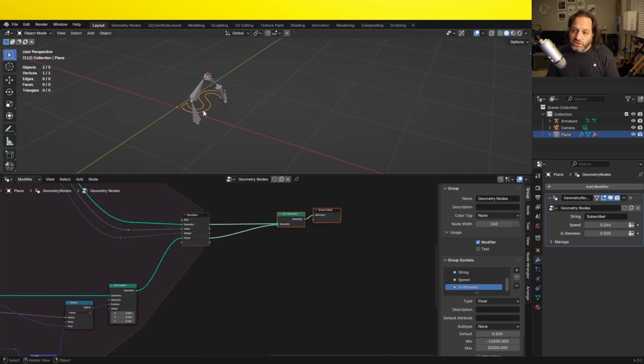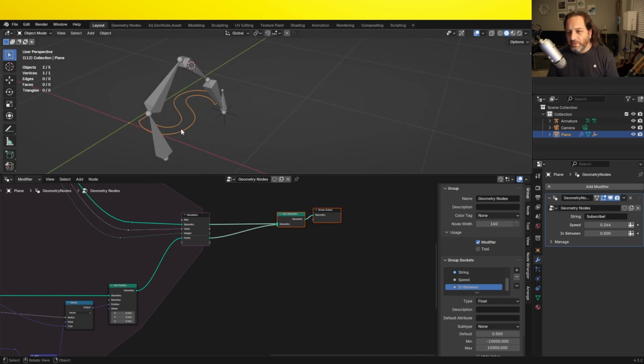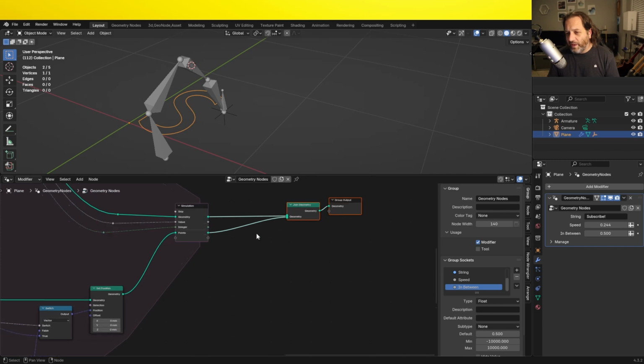One thing we're going to want to do is to have these text curves be able to be rendered in some way. Now, you of course could do this by doing a curve to mesh and doing mesh outline. Another way you can do this, now that Grease Pencil is compatible with geometry nodes, is you could turn these curves into Grease Pencil strokes. So let's go ahead and do that.